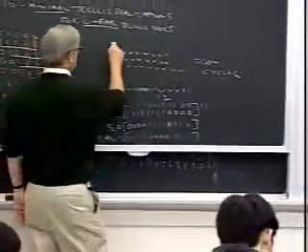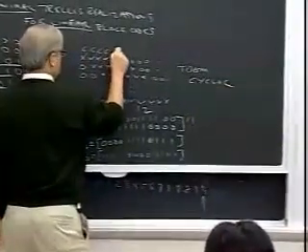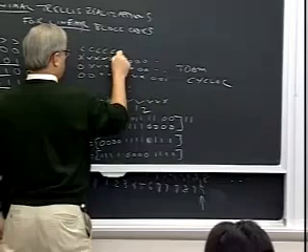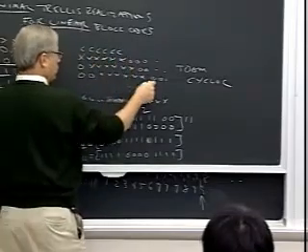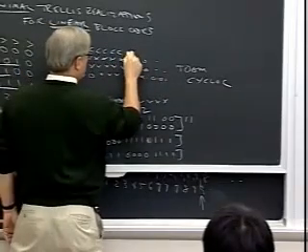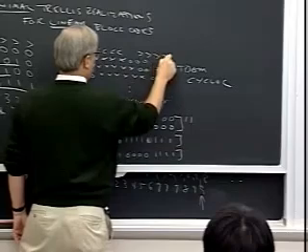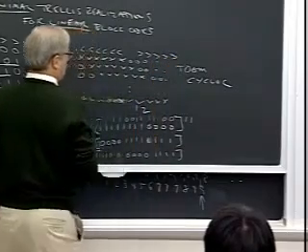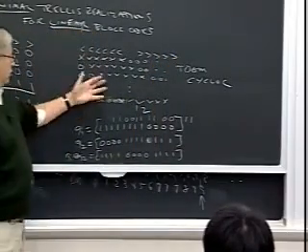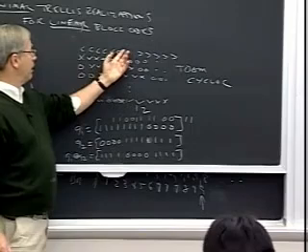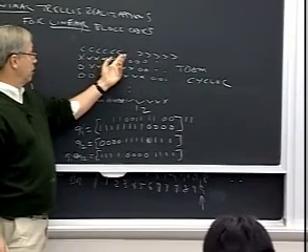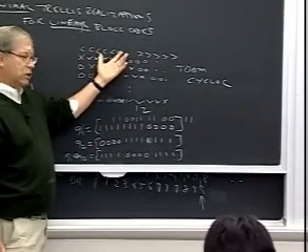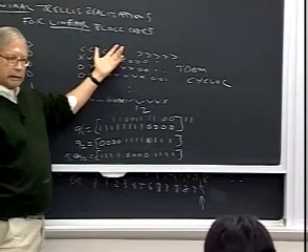And it's always going to have this worst case. All the branch diverges are going to occur over here. Then you may get nothing for a while, and then all the merges over here, which, if it's a rate less than 1/2 code, means that the trellis complexity is basically going to be 2 to the k.